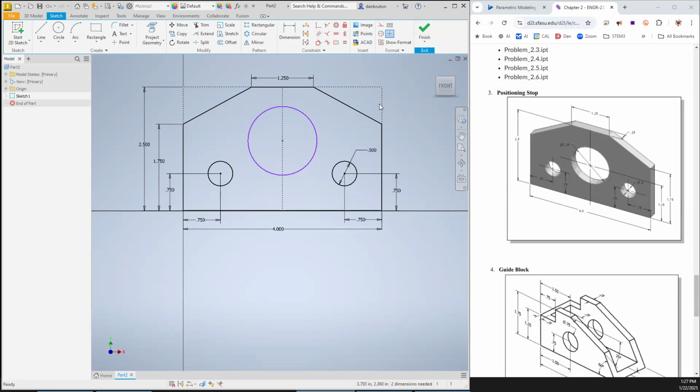When you're uncertain about what the constraints are, you can try two things. One is to try to move it around, and the other is to try to resize it. So you can see that we can move it and resize it. Those are the 2 degrees of freedom. But we know what to do, right? Just grab the dimension, going from here to there, then going off to the side. Fortunately, that's going to land out in a nice spot, 1.25. And then on the radius right here, we want that to be 1.25 in diameter.